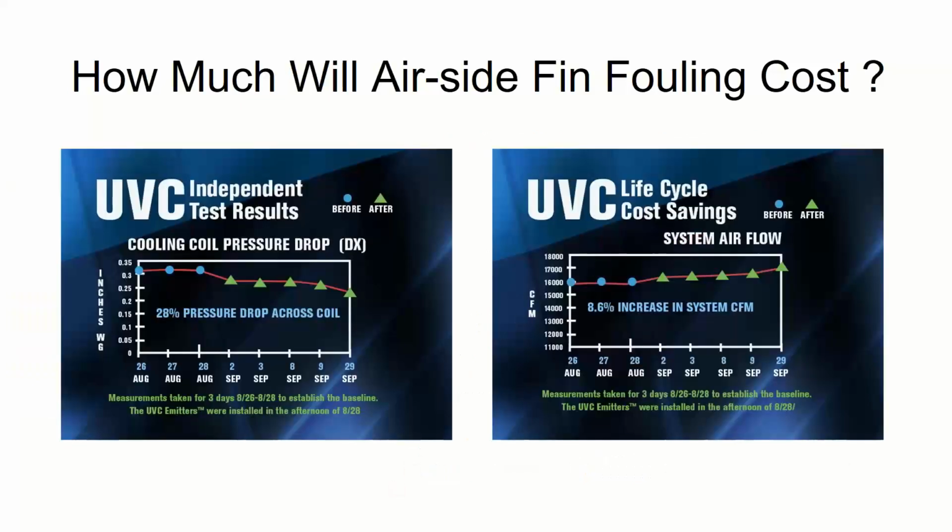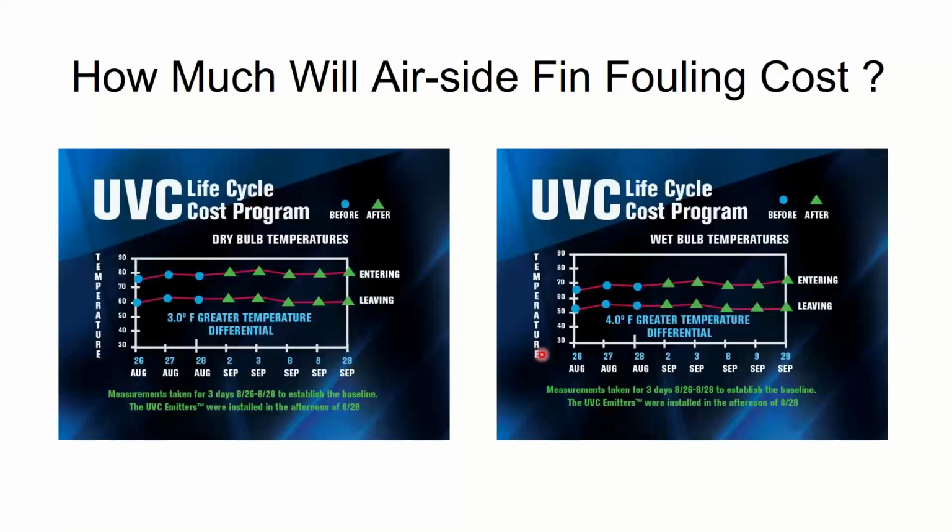And then also stolen from our competitor at Sterile Air. Give them credit because I stole from them. But they have a couple quick slides here that show you improvement of pressure drop across the coil by having UV light cleaning it, improvement in airflow, improvement in dry and wet bulb temperature control. Lots of benefits to keeping the coil clean, other than just not having something gross on your coil.